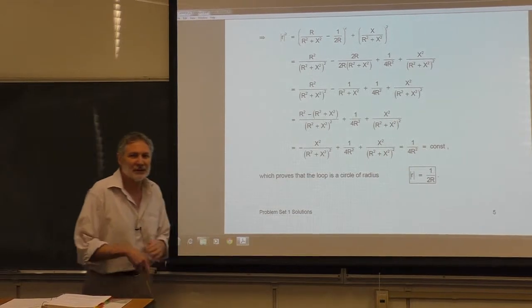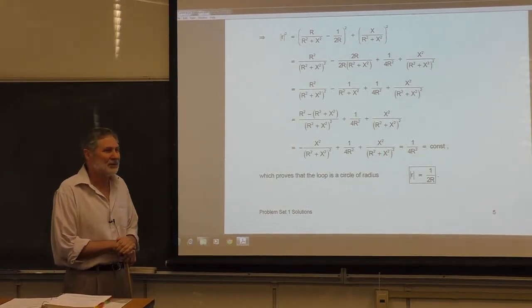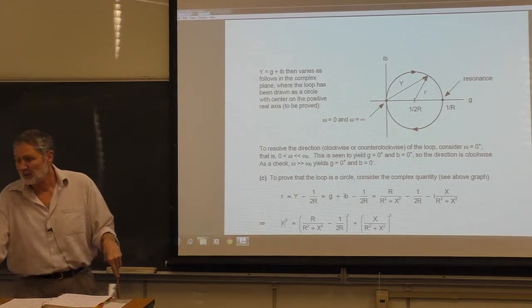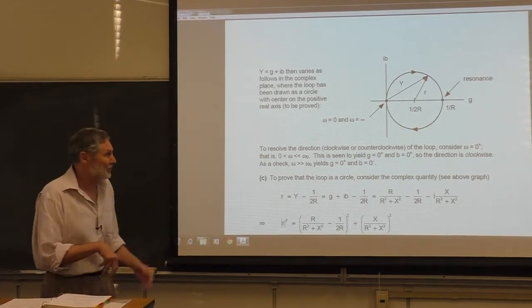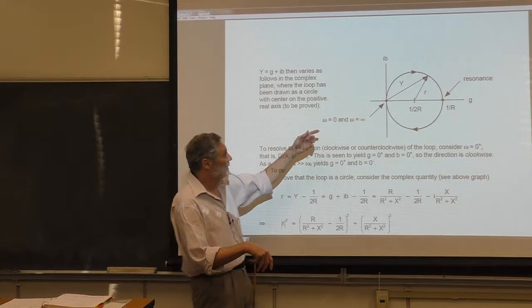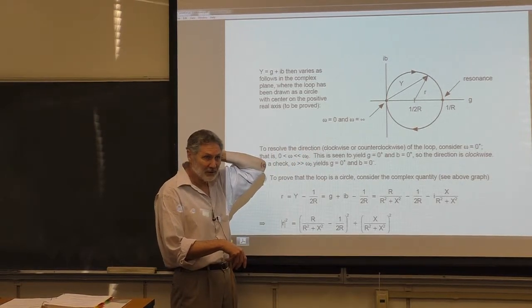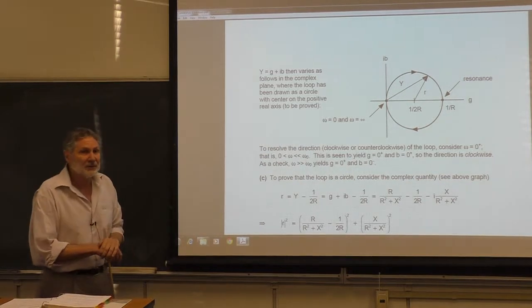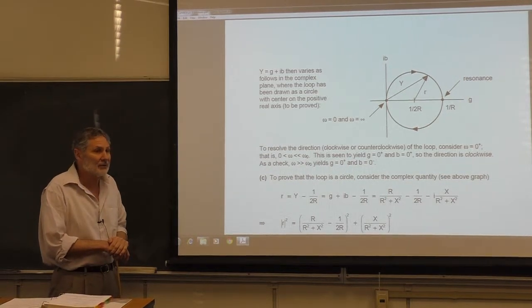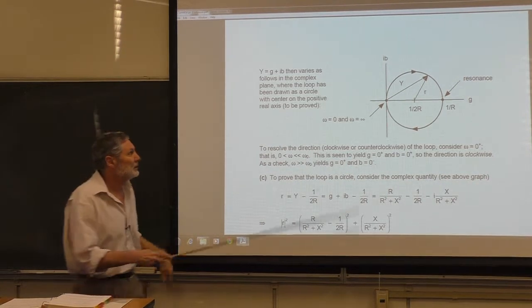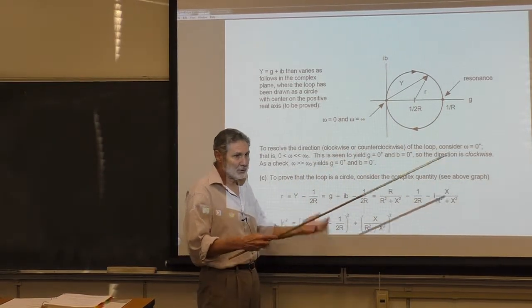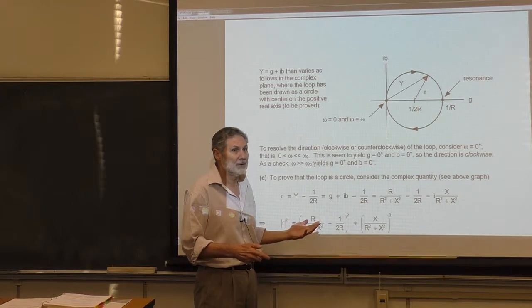And now, we'll talk about this later in the course, now you can see why this can be useful. Experimentally, you often want to know all the parameters, in particular this mechanical resistance here. So if you've got this actual transducer, you can plot the admittance, and we have electrical boxes, equipment here that will plot admittance.